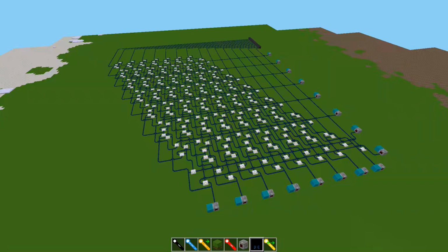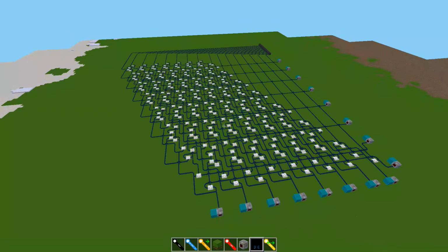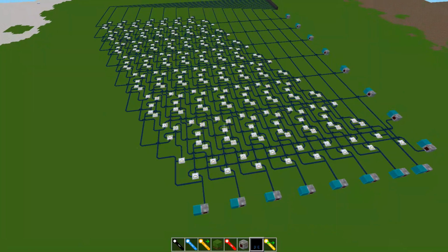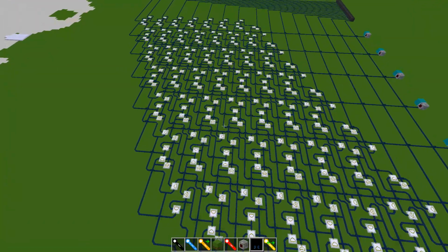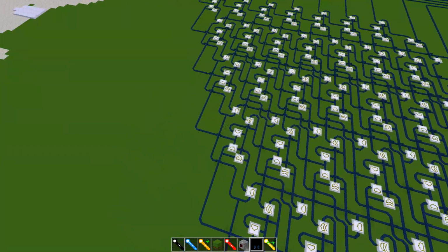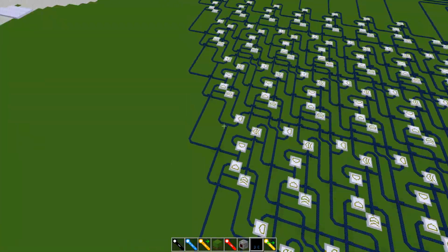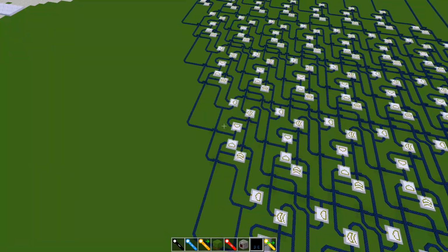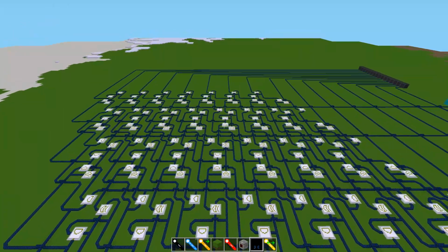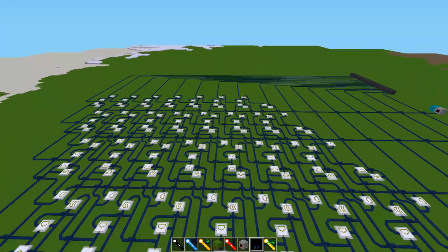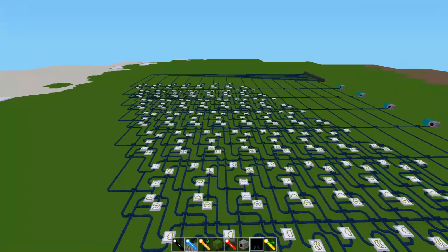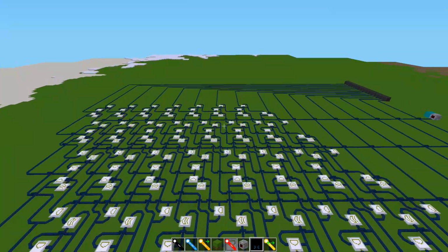What is shown here is an 8-bit multiplier with a 16-bit output. Of course, you can change the number of bits in the output to a lower number by moving what is here on the left, doing the circuit in a way that looks like this, just moving it to the right and doing it in a perfect straight line. For example, to get an 8-bit output, you're just truncating the result to 8 bits.